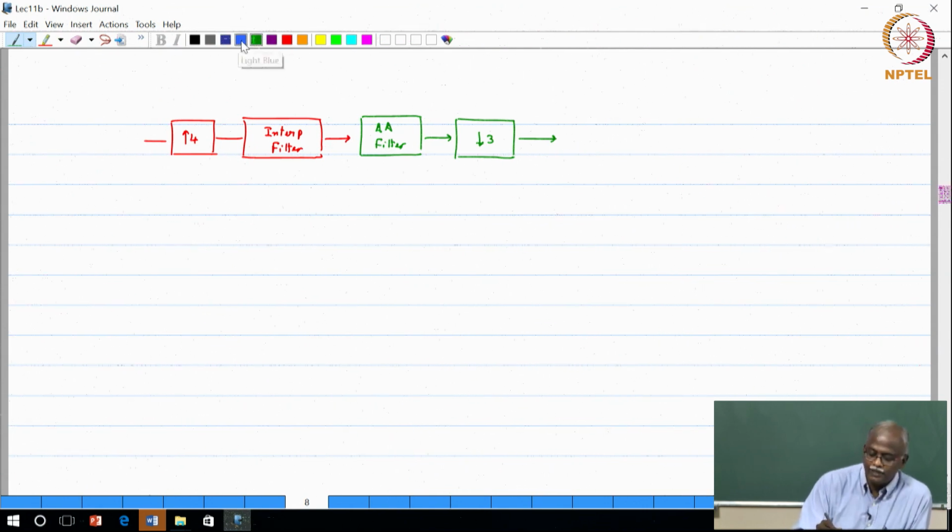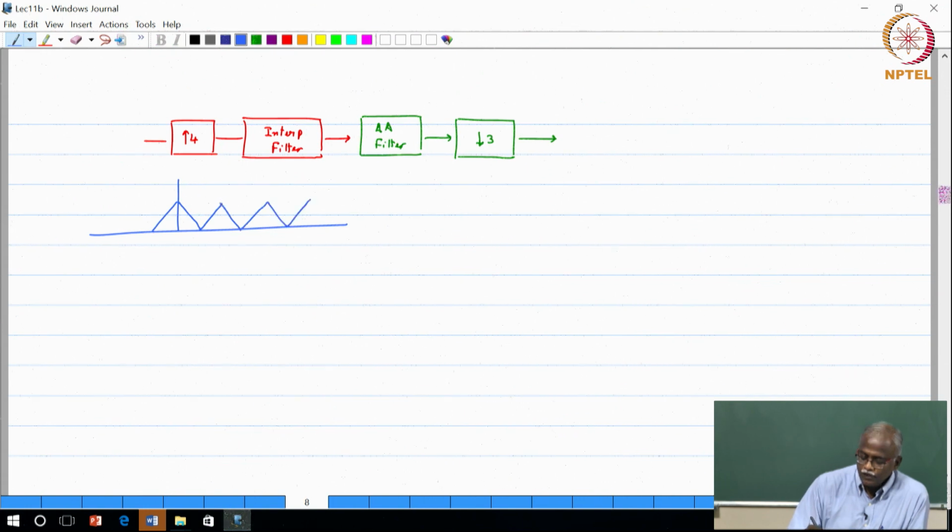Okay. So, here is a quick run through of it, we will just do it in the spectral domain, that helps us. So, the first step after the upsampling process, I get 4 copies of the signal. The input signal was at 12 kilohertz. So, when I upsample by a factor of 4, it became 48 kilohertz. So, this is still 6 kilohertz minus 6, this has now become 2 pi for me. Okay. If this is 2 pi, then this point is pi by 4, am I right? This is 2 pi, this point is pi by 4. So, the first stage of the process is here.